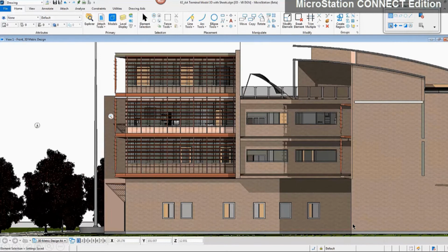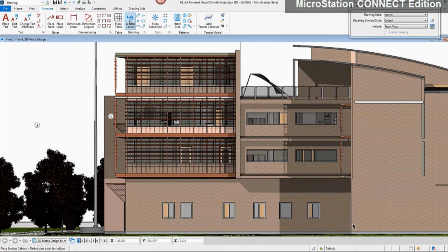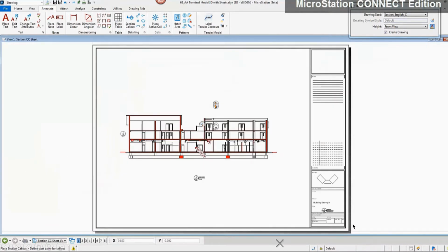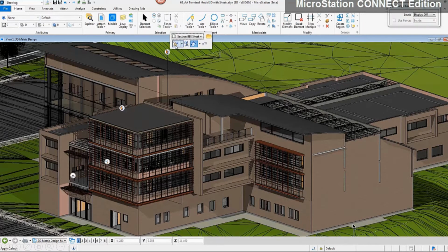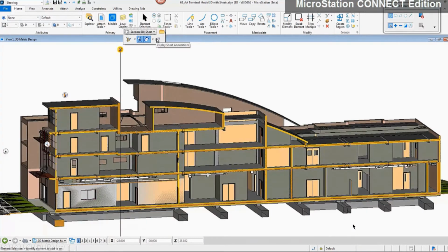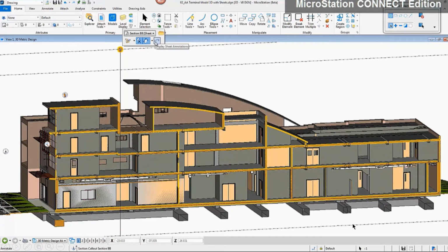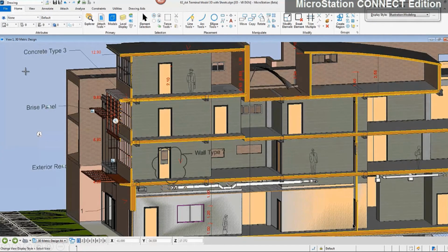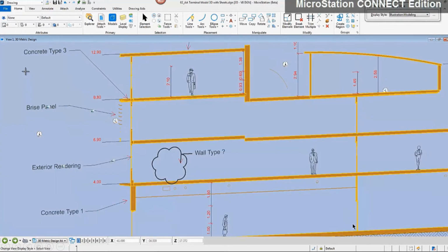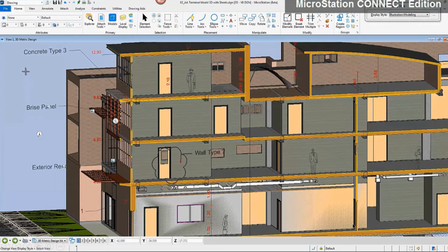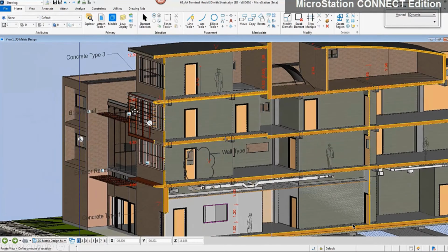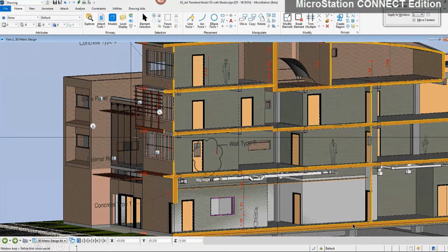So with parametrics, we can then go directly to our project deliverables, where we are interested in taking our three-dimensional models and creating two-dimensional sheets. And we've done a lot to make this workflow a lot faster, so it essentially ends up being one click with live sections within your three-dimensional model. You can then cut your three-dimensional model to that section and annotate it. So for example, you can add in dimensions, you can add in things like patterns, you can certainly add in notes with leaders,